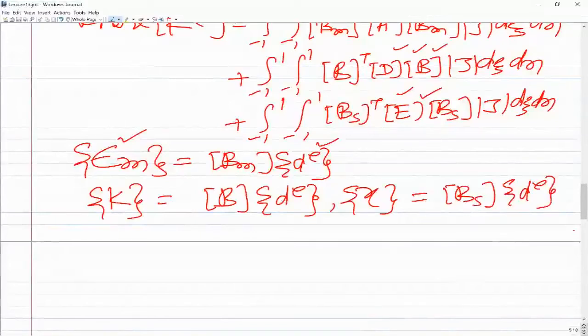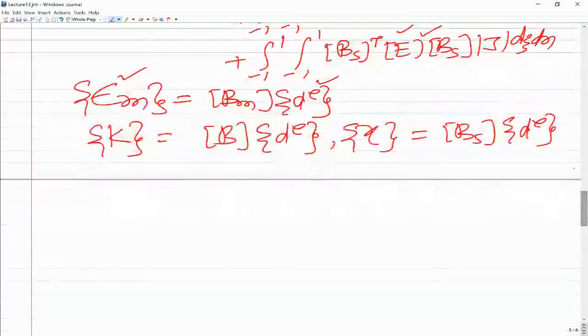Now, the main thing, as I talked about at the beginning, is that when you are using different elements, they are in different planes, so the local element coordinate system is different for each element. So before assembly, you will have to transform the element level governing equation. That's the main thing I wanted to talk about: the transformation from element local coordinate system to global coordinate system.